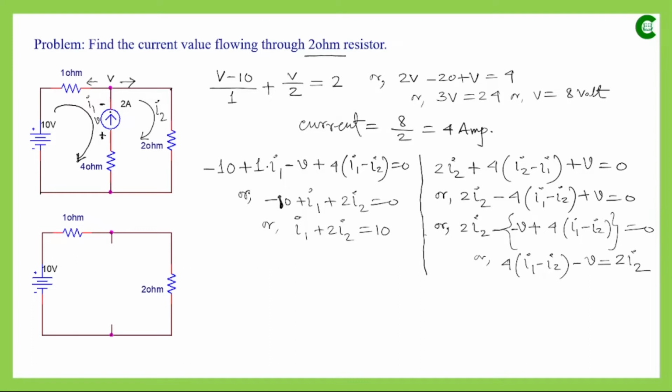We just open that path, and when we remove this current source, no current will flow through this resistor also. So in total, this current source along with this resistor in series will be removed from that path. It is assumed as if it is not there, and that way it forms a bigger loop or bigger mesh. So that is the concept of supermesh.